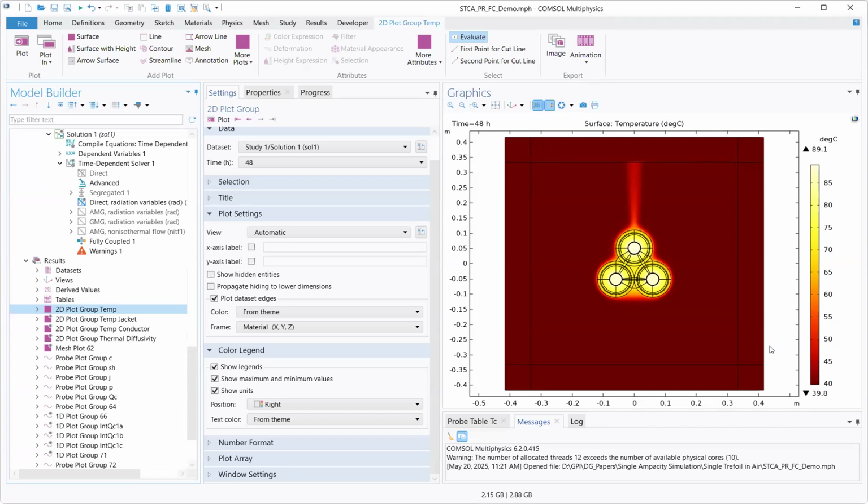But that's in general, in any FEM software. It's not just one airbox, or should I say model domain, right? It's not one size fits all, right? Whatever you want to call it, simulation domain, model domain. In this case, it is the airbox, right? So in this case, I would ensure that this minimum temperature is not less than my boundary of 40 degrees. So in that case, it's just, yeah, I got a question?